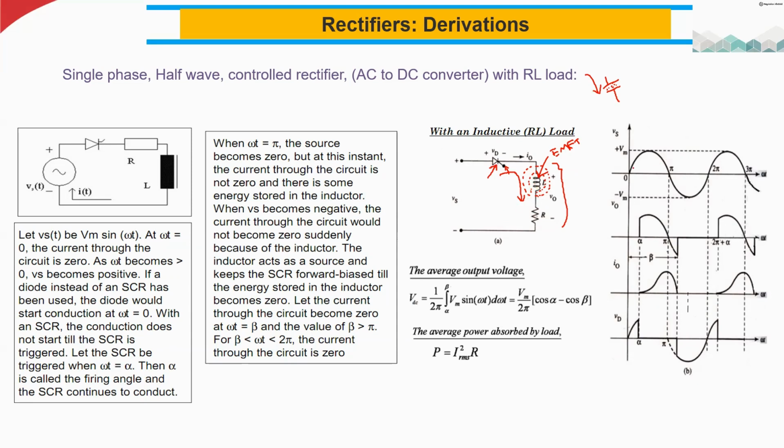That is the first half cycle. In the second half cycle, what's supposed to happen? You are reversing the bias, right? So this SCR should not conduct anything. But once the polarity gets reversed in the negative half cycle, this inductor already has some magnetic field, some energy inside.